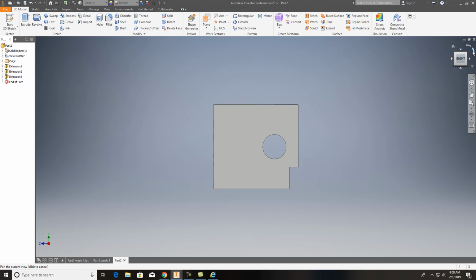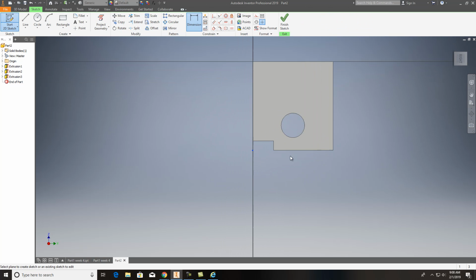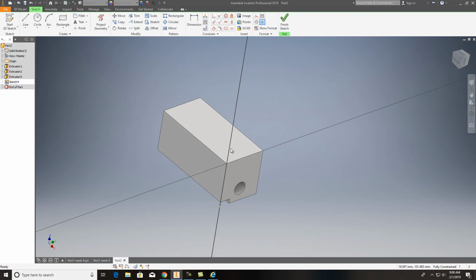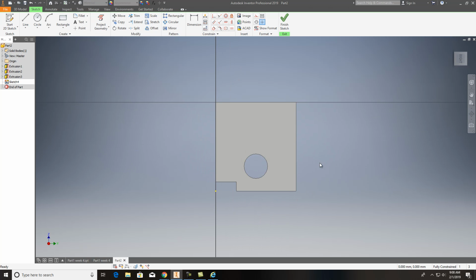And also, I'm just going to turn this thing and look at it again because I want to put another sketch on it right there, right on the face of that. You can see the sketch is right on the face of this again. I've got a cut of 30 degrees coming down through here. So I'm just going to put a line something like that. And we've got to do some work on it. My dimension from here to that point right there is going to be 10. So I get that put on there. And this is going to be a line of 30 degrees. There's my 30.